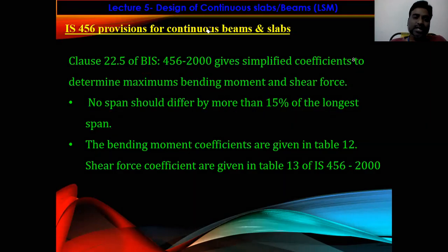And if it is satisfied, then you can calculate the shear forces and bending moments using the coefficients given in IS 456-2000, Table 12 and Table 13. Table 12 gives the coefficients for the calculation of bending moment, and Table 13 gives the coefficients for calculation of shear force, right?